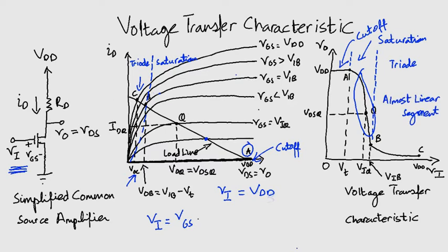We also see how the voltage transfer characteristic helps us understand how the MOSFET can be worked as a switch. When we want to keep the device off, we keep our input voltage lesser than Vt so that the device is in the cutoff range. So simply altering the input voltage, we can achieve functionality as a switch. Hope this topic is clear to you.